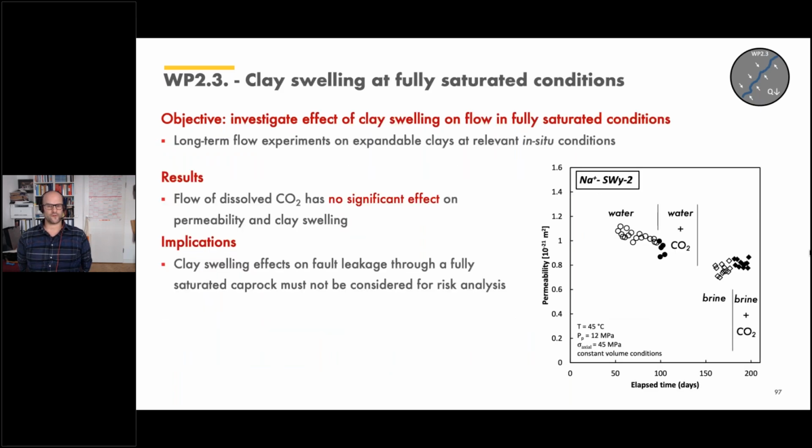In a follow-up experiment, we used a plug that consists of up to 100% swelling clays. We did a couple of permeability experiments, as I said, at Aachen University, where we first injected just pure water, giving a permeability of 1 nanodarcy. Then we co-injected CO2, showing that the permeability isn't changing.